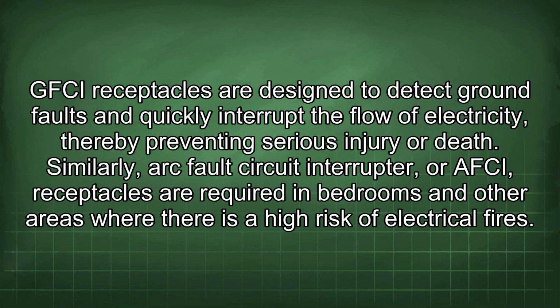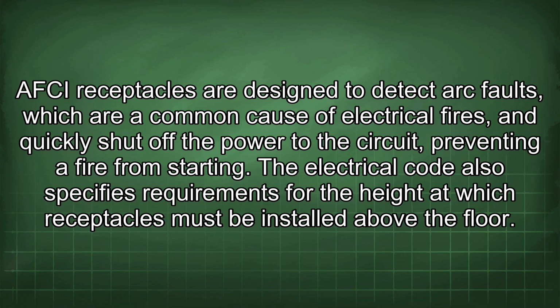death. Similarly, arc fault circuit interrupter, or AFCI, receptacles are required in bedrooms and other areas where there is a high risk of electrical fires. AFCI receptacles are designed to detect arc faults, which are a common cause of electrical fires, and quickly shut off the power to the circuit, preventing a fire from starting.